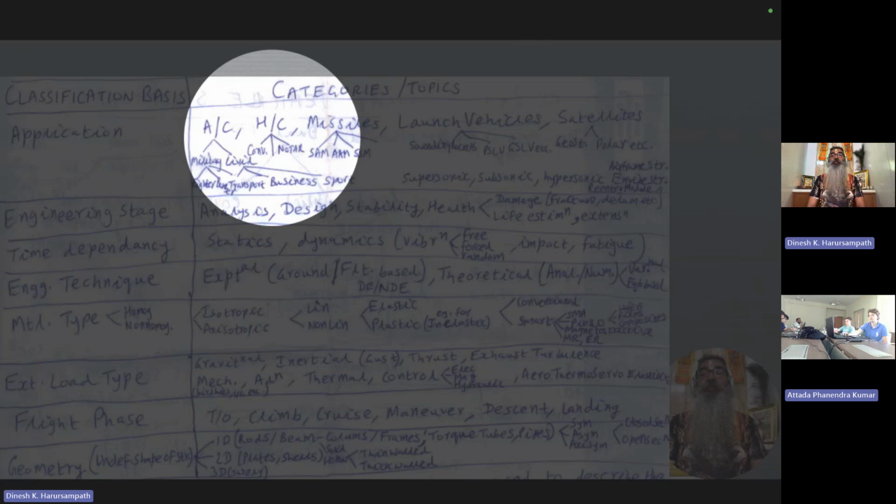Okay, so which means that we should be aware, in a structural analysis, of how these things get coupled. So I can't study extension alone separately and torsion alone separately. I have to study both of them together, because one causes the other, and without knowing how they are related to each other, I would be just working on a theoretical problem of no practical relevance.